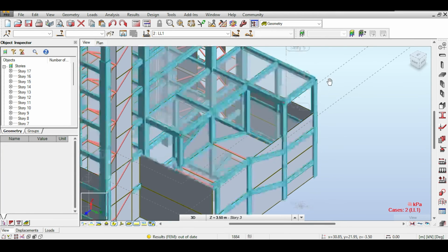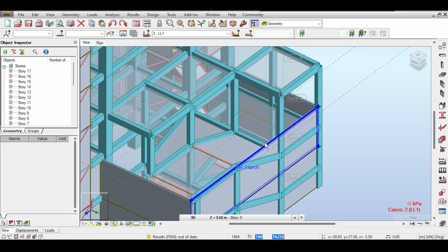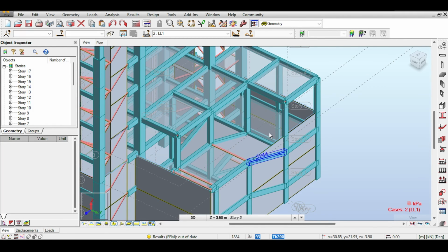Also, the architect totally forgot to give a slab on top of the car ramp, so I have done one here. One very important detail you need to understand in car ramps is that you need some sewage system, some stormwater drainage system, because when it rains, of course, the water will seep through the ramp, and you need a water collection system here. This, of course, is not part of my series because I want to deal with the structural aspects.